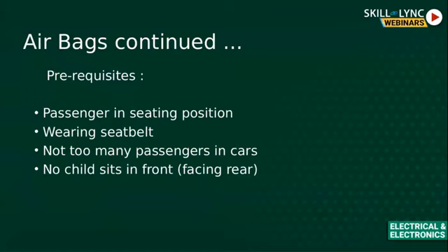Secondly, imagine you have a car with airbags installed, but you have parked your car and gone to have food in a restaurant, and unfortunately a rogue driver comes in and hits your car when it is parked. Here I want to mention that airbags are one time use. When an airbag is deployed in your car, you cannot reuse the same airbag. So when your car is parked and somebody hits it and nobody is inside, there is no need to deploy the airbag. How does the algorithm check this? It will see if the seat belts are plugged in, because a parked car will not have a seat belt plugged in as there are no passengers who need to use the seat belt. And that's why wearing the seat belt is important.